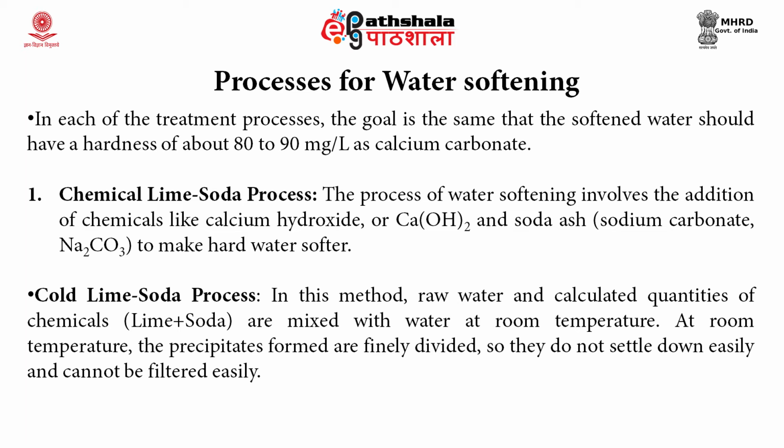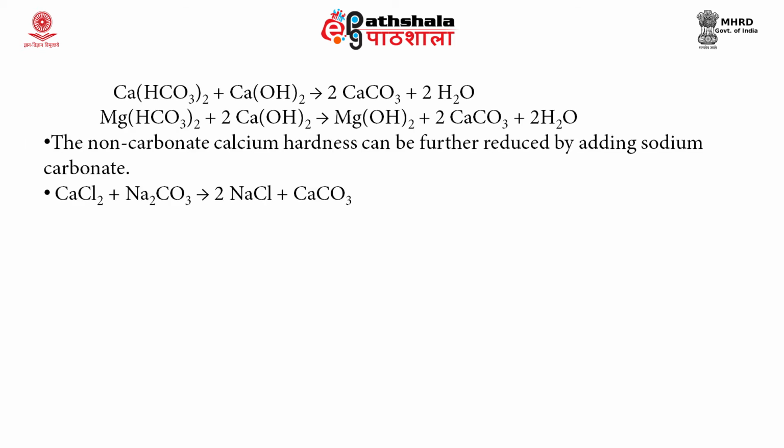At room temperature, the precipitates formed are finely divided, so they do not settle down easily and cannot be filtered easily. At room temperature, calcium bicarbonate present in the hard water along with calcium hydroxide, that is lime, forms calcium carbonate. Similarly, magnesium bicarbonates also form magnesium hydroxide and calcium carbonate, and the non-carbonate calcium hardness can be further reduced by adding sodium carbonate.